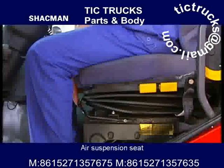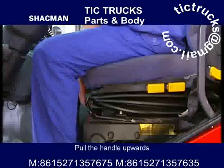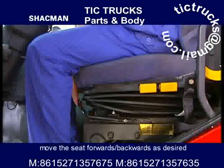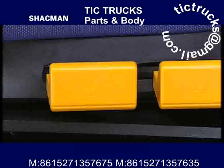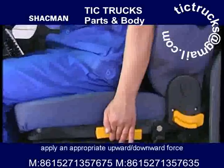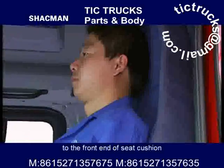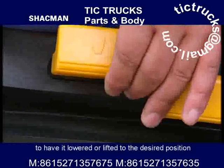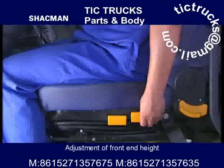Air suspension seat. Adjustment of fore and aft position. Pull the handle upwards. Move the seat forwards or backwards as desired. Then release the handle. Adjustment of front end height. Hold the handle upwards. Apply an appropriate upward or downward force to the front end of the seat cushion to have it lowered or lifted to the desired position. Then release the handle.